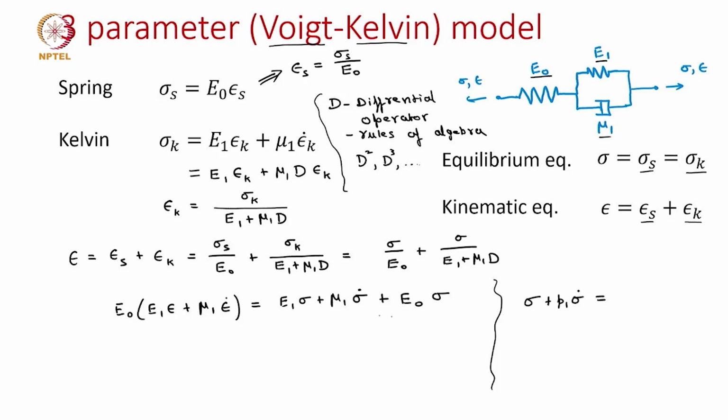Since I notice in my equation the derivatives of stress stop at the first derivative, now we move to the right side of the equation where we write the strain terms. So, coefficient times the strain plus another coefficient times the strain rate. Again the strain rate stops at the first derivative, so we stop at Q1 coefficient. So, this we are calling it as the standard form.